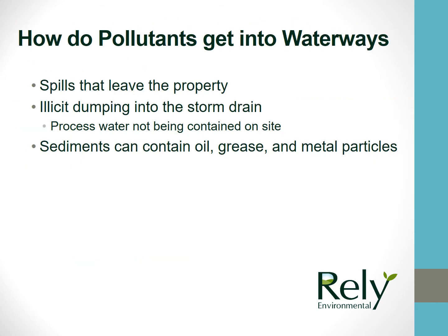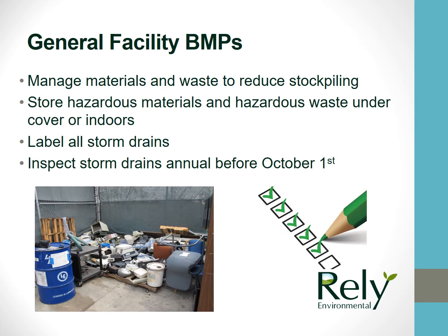Pollutants are able to enter waterways through uncontained or improperly cleaned spills that leave the property, through illicit dumping into the storm drains, including processed water not being contained on site, and when sediments that contain oil, grease, and metal particles leave the property. Examples of general facility best management practices include managing materials and waste to reduce stockpiling, storing hazardous materials and waste under covers or indoors, labeling all storm drains, and inspecting storm drains annually before October 1st.